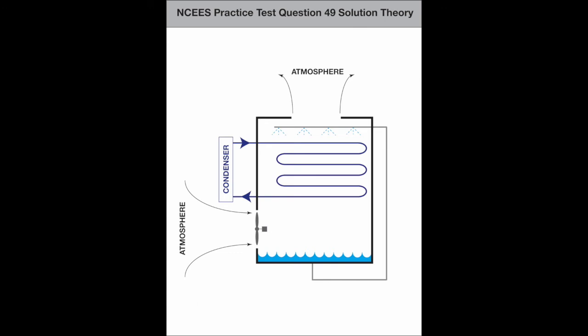So while there will be water used here, you should be focused on the water from the condenser, used here. It's this exiting water temperature that you are supposed to solve for. Cooling tower analysis links steady state energy flow of the air, which flows here, with the water, which flows here.